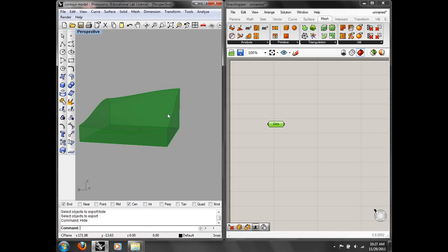And then I'm going to put a label right in the center of each of those. I could put the two things on two different layers when I bake them. So one layer is cut, and that's going to cut the outside, and one layer is score, and that's going to be the label part, right? So I'm going to have the labels parametrically. And then I can adjust the number of contours I take, and it's going to instantly create that cut sheet for me, okay? Let's see if it works.